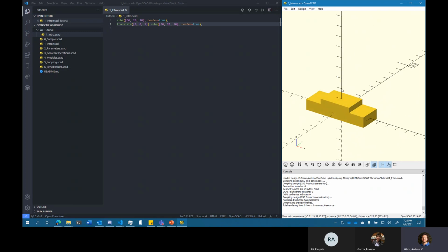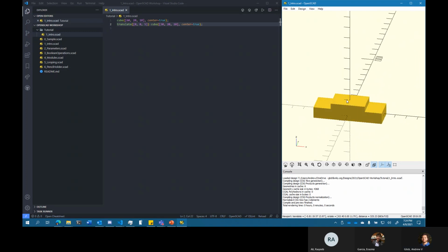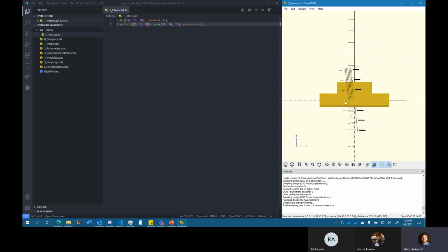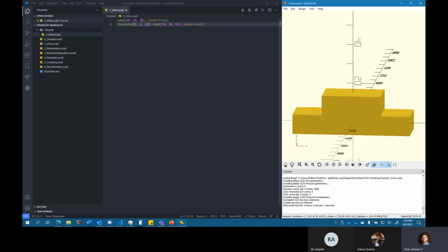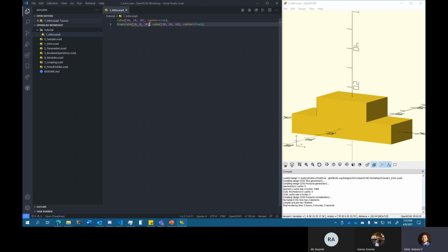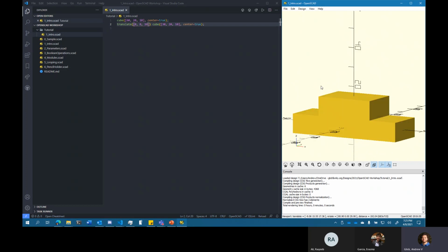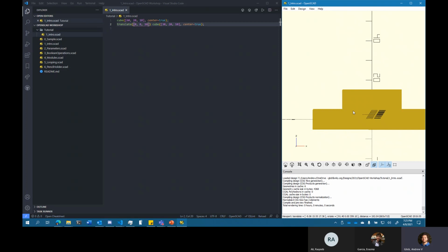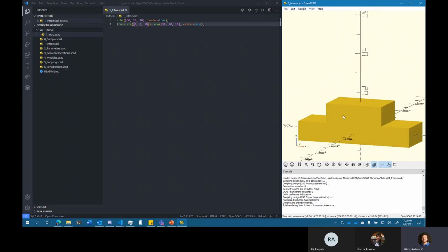So now we have the two boxes. We can increase this number even further. This gets to 10. But if you notice that the boxes are 10 tall, or 10 units in the z direction already, and it can be kind of confusing to OpenSCAD when you have two faces intersecting each other right there in the middle, because they're both at the same height.